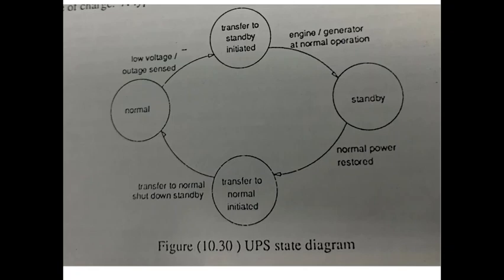At lower levels, up to a few kilowatts, an electromechanical relay may be used. But at high power levels, a mechanically operated switch may be used. The important point is that the load must be transferred as soon as possible to the standby source. For high power applications, a circuit breaker must be used for the transfer switch.